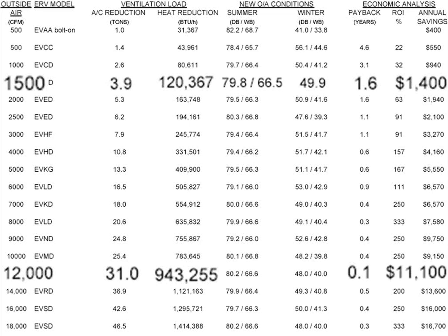Paige writes in asking if these economic analyses included labor or just equipment cost. This included both. So this was everything in all. This is cost. We worked with contractors to develop this because we're a distributor. We worked with a couple of contractors to develop this. This is the cost difference of buying a new, smaller rooftop, right? Which is a credit in that case instead of buying the big rooftop. The cost penalty of buying the ERV, any equipment used to link those two together, and the installation labor associated with installing the extra ERV.